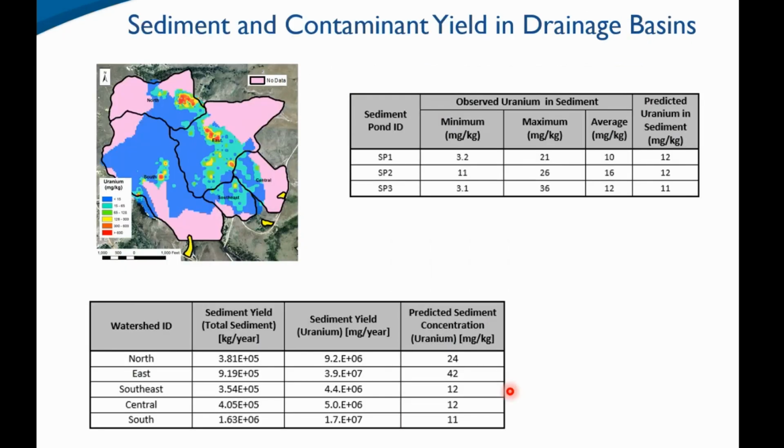From this, the point I want to make in terms of technology is to link this with my presentation yesterday morning, where you can link this with the upland erosion mapping that we have. And you're going to say, I'll erode, let's say, 1 kilogram of this soil on a mean annual basis. But your contamination level is going to tell you that you have, let's say, 1 milligram per kilogram of arsenic, or maybe it's uranium, or maybe it's radium, or whichever contaminant. You say, well, I have 1 kilogram, times 1 milligram per kilogram. So you expect 1 milligram of arsenic to move out, being eroded from those upland areas.